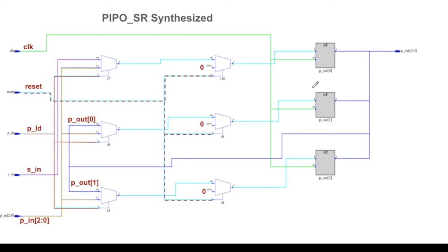And the interesting part of this is all of these muxes. And these muxes are what the if turned into. And so if you don't know, a mux is something that uses a control signal here on the bottom to select which input becomes the output. So on this mux here, if the control signal is a 0, the top trace becomes the output, and in this case goes on to be the input of the next mux.